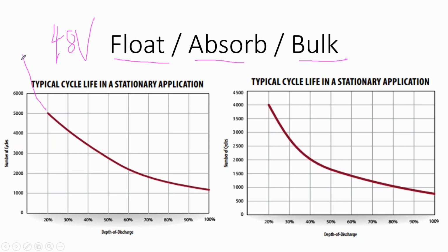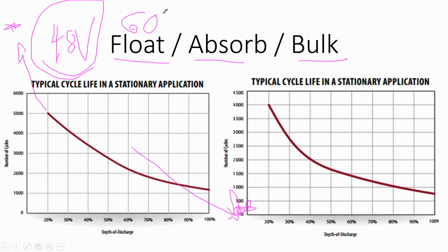Up at the top of this curve, you're at full voltage, and at the bottom of this curve, you'd be at no voltage. What's interesting about the 48 volts is that it's the nominal voltage. It's not the maximum voltage. And so these batteries might actually be 60 volt batteries. It's just that they're normally operating under load in this 48 volt range.